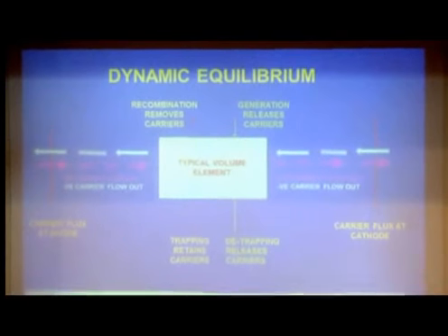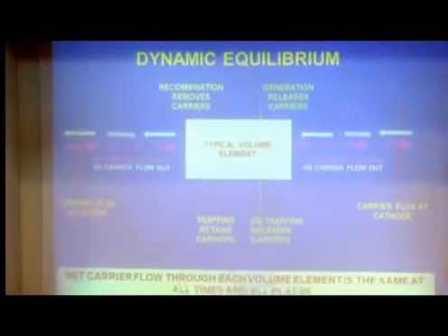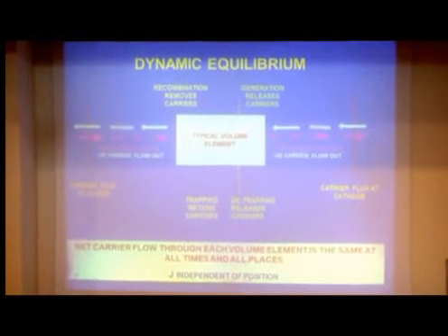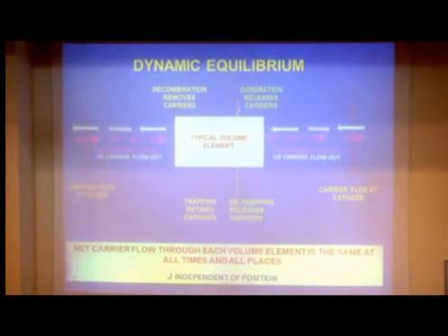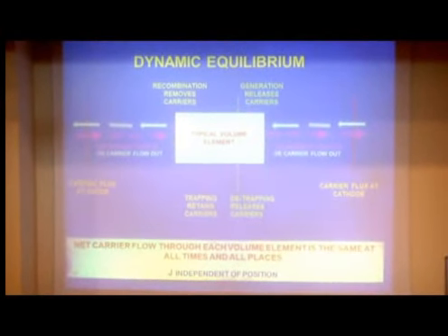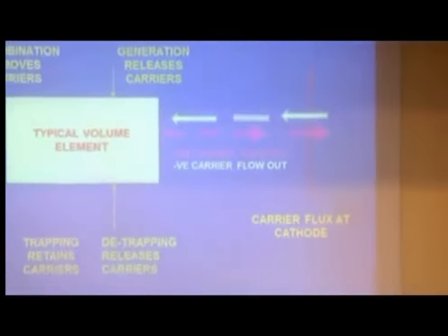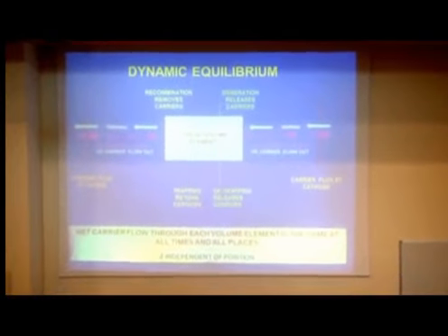Now, at low fields, crossing your fingers and a little prayer and a few other things as well, we can just about persuade ourselves that at the very least each of these processes is a linear function of the field. That's at low fields. It may not be true, but we can perhaps hope it is. When we come to high fields, that's not going to be true. We're going to get different field dependence for injection, maybe different field dependence for extraction, different field dependence for the way that the carriers move, perhaps different field dependence for mobile ions compared to mobile electrons.